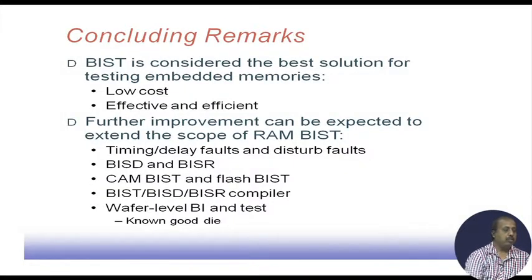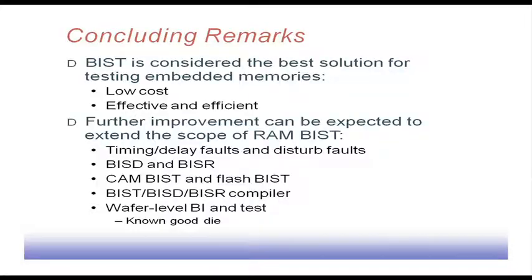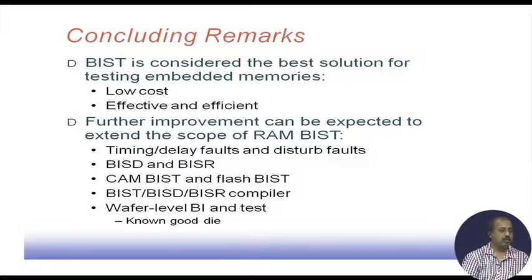So, to conclude, BIST is the best solution for testing embedded memories, because the cost is low and it is effective and efficient. If you are using ATE for testing so many memory locations, it will take a lot of time. Further improvement can be expected. We can have some timing or delay faults and disturb faults, so they can be covered.